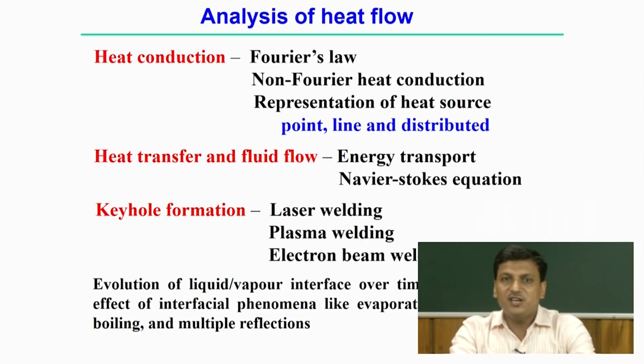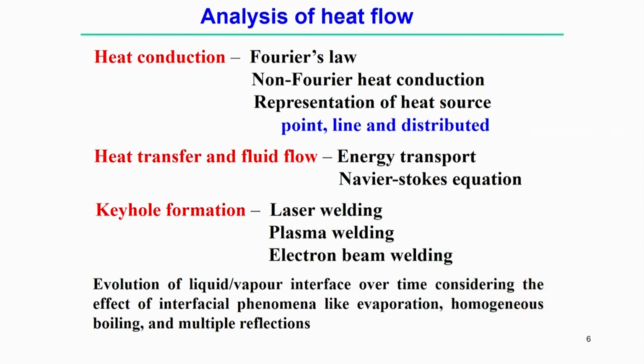Now, for the analysis of the heat flow, what governing or constitutive equations can we use to estimate the temperature distribution within the domain of interest? In the welding process, as the governing equation we consider the heat conduction equation, Fourier's law of heat conduction, and we can solve for the temperature.